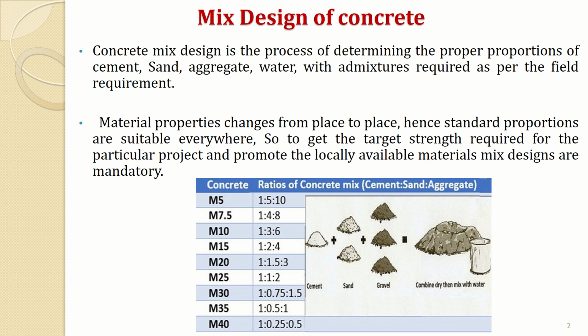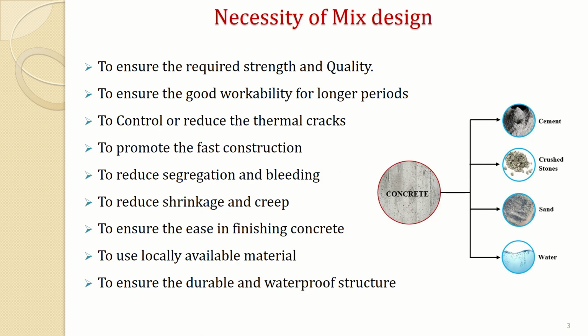Hence, as per the locally available material, whatever sand, aggregate, or cement is available, we must test all the properties of the material in the laboratory and use the same material for the concrete mix design, so that that particular project or concrete will be economical. In other words, concrete mix design promotes the use of locally available materials. So that is one of the important advantages of concrete mix design.